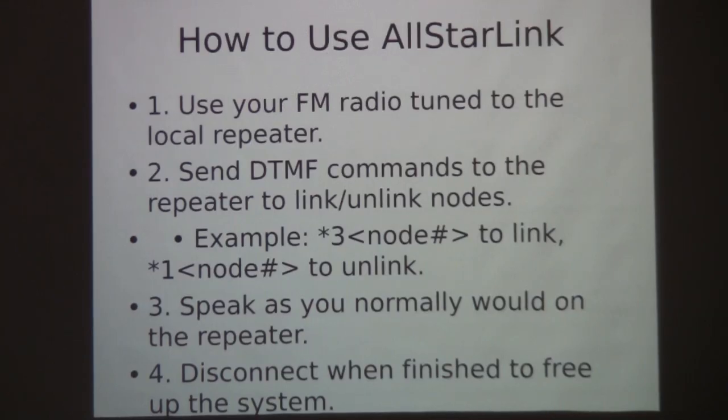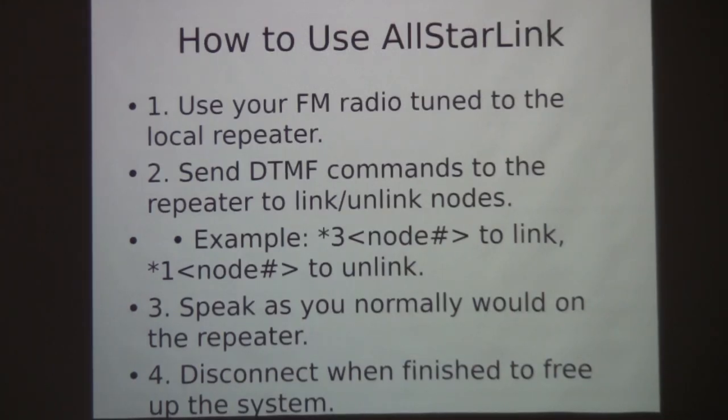So you use your FM radio tuned to the local repeater. You send DTMF commands to the repeater to link and unlink nodes. For example, *3 and the node number will link it. *1 will unlink it, and then you just speak normally as you would on the repeater, and you disconnect when finished so you can free up the system again. I can set up a timeout on it, but I don't think there is one right now.